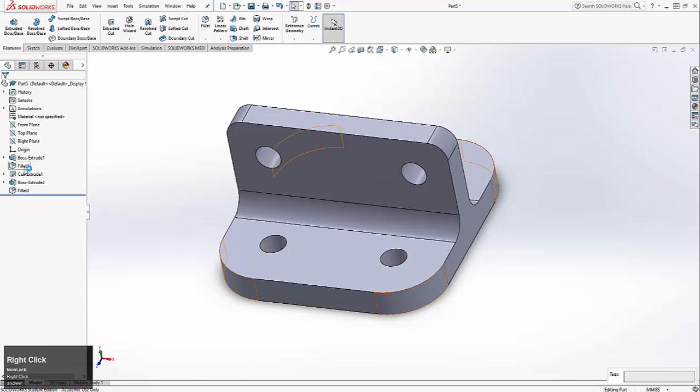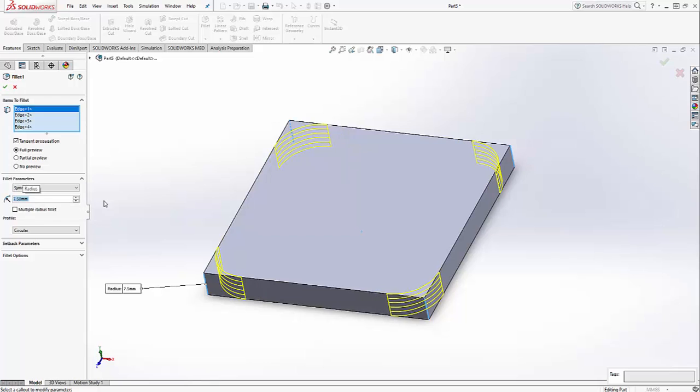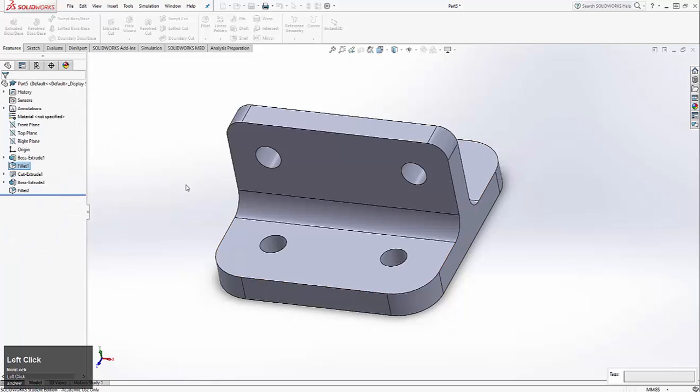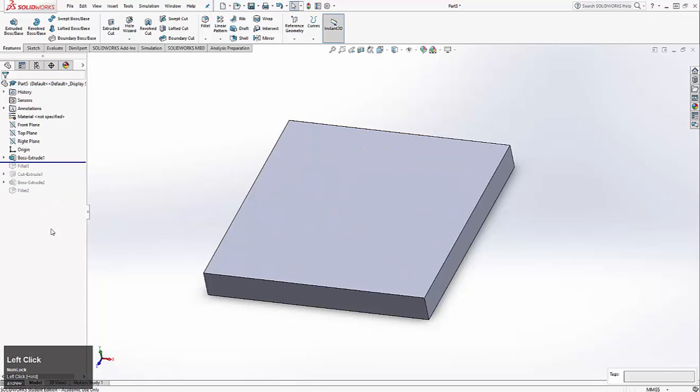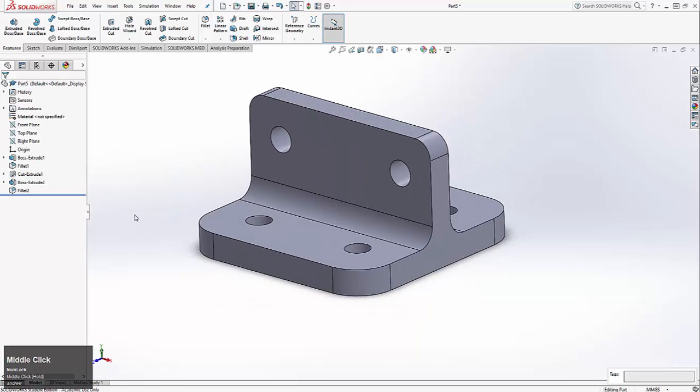Right, that's what I was going to do. So take the fillet, edit. It goes back in time, and I want this to be 7.5, and it's going to change all of them, and there we go. And you can achieve a very similar thing with the rollback right here. So I want to roll back to there, or there, or there, and another couple final little tiny things.